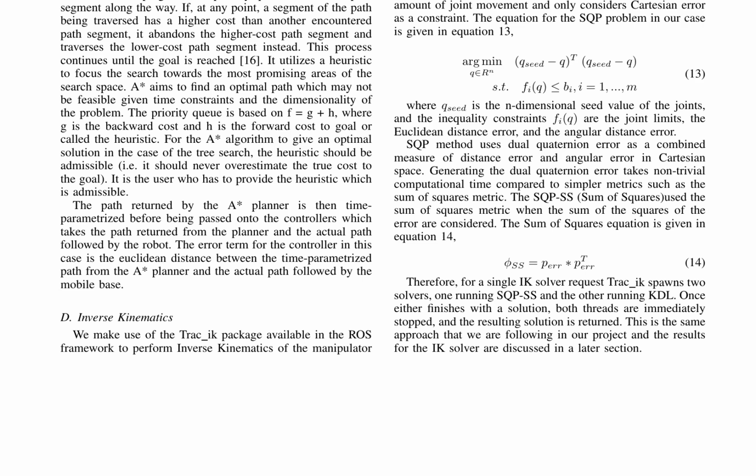Finally, the paper discusses the control of the gripper action, which involves commanding the gripper to a fully closed or fully opened position with specified effort. The gripper command takes in position and effort as parameters, and the grasp strength is determined by the maximum effort. To pick up objects, the authors controlled the effort generated by the gripper in the Fetch robot.